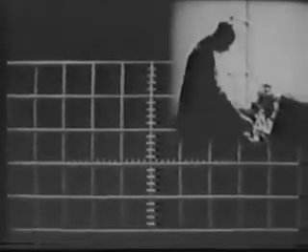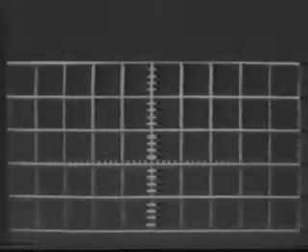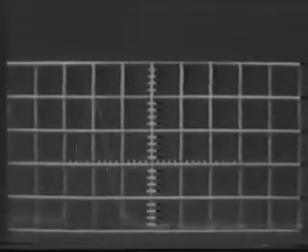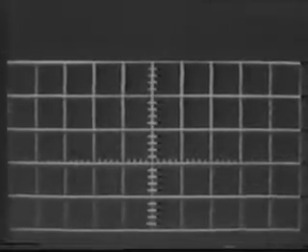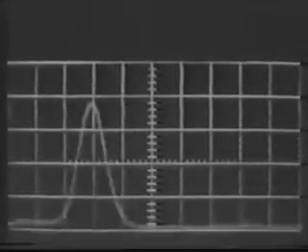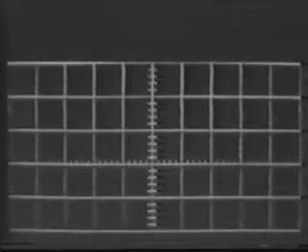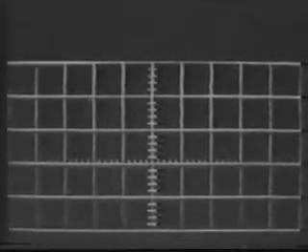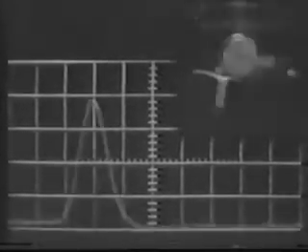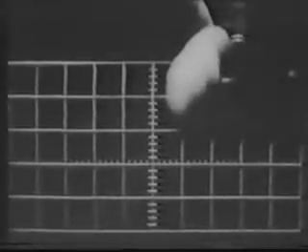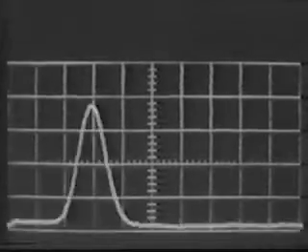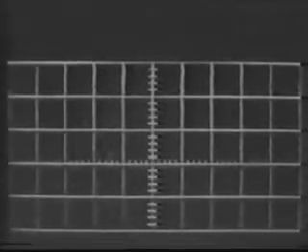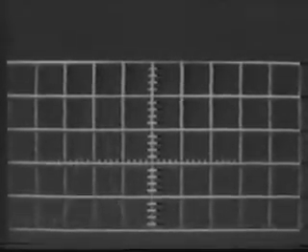Now we're ready to plug in our detector. Look at this. When Bill and I first saw such a pulse, we really knew we were detecting holes moving down the germanium bar. To show you that this pulse is actually what we thought it was, let me point out the following. First, when I prevent the light from reaching the bar, the pulse disappears. Second, there is a long time delay between the light flash and the arrival of the disturbance at our detector.